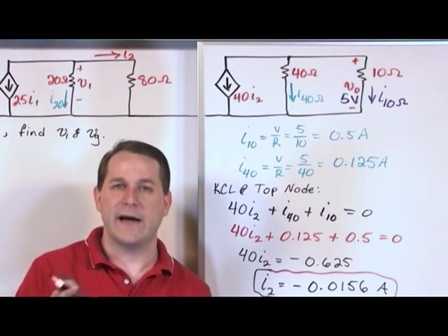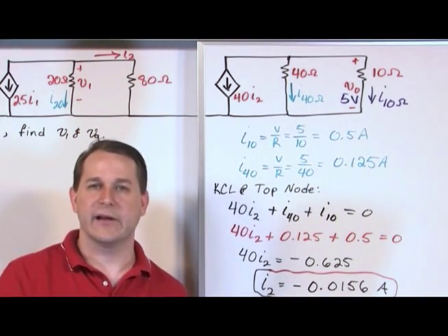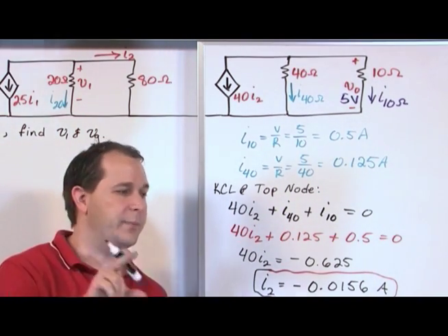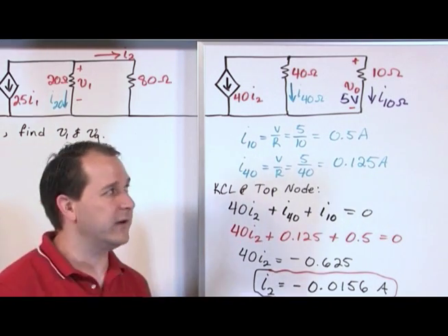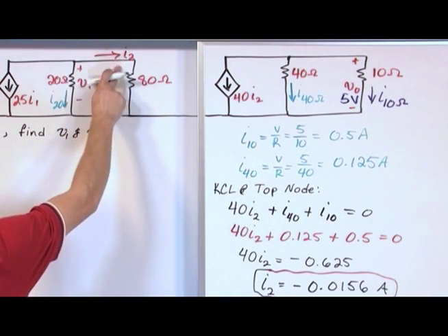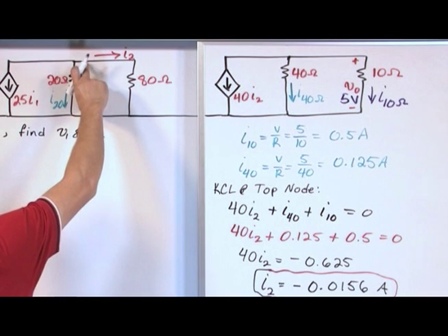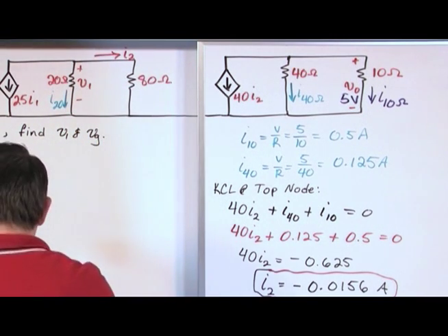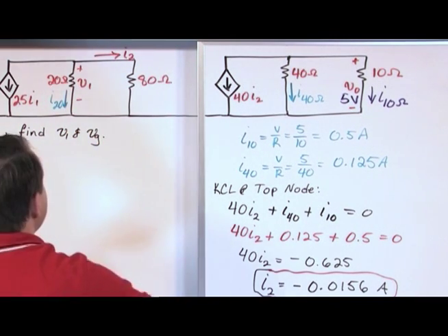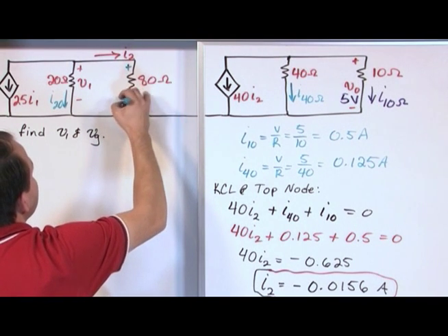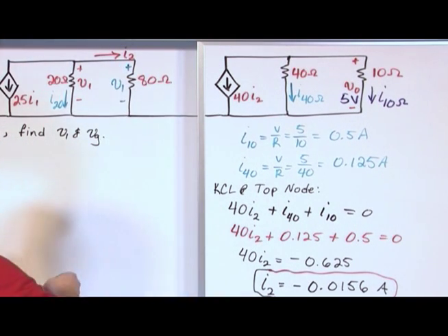Now, anytime you have two things physically connected with wires like that, the voltage will be the same across them. That's what voltage is, right? Now, if there were a resistor up here, then this would not apply. But since they're connected with the wire, then what we really can figure out, I'm going to draw it here, is that really this voltage across here is also V1. I'm drawing that myself because it's not given to us in the problem, but you deduce it from what you see.